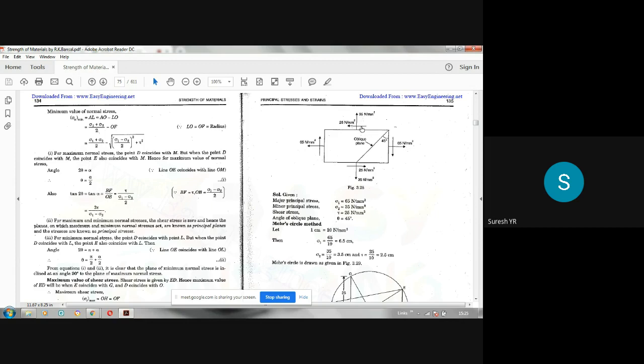And the value of tau is nothing but shear stress. So here shear stress always acts in a complementary manner. That means if I take the shear stress like this, on the other side, it will be in the opposite direction. See, it is acting towards left here. On the other side, it acts to the right. And here, on these two sides also, shear stresses will be acting. And how do they act? So here, it is acting towards left. So it should act upwards, so that this arrow and this arrow meet. Similarly, on the other side, it will be acting downwards. This arrow and this arrow, they will meet. So shear stress will be acting on all the four edges. Tensile stress or compressive stress will be acting perpendicular to the edges.